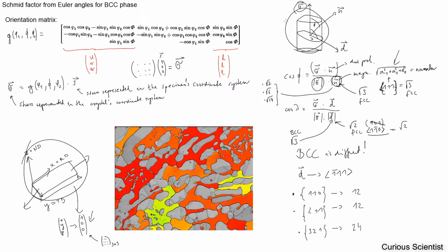And then what we can do is, for example, calculate the Schmid vectors with this formula here, or basically these two formulas. Sorry for the confusing jumps between the different parts. We also know that the Schmid vector is defined by this equation, the product of these two numbers, this guy and this guy. So this is the Schmid vector. And then we assign a Schmid vector to each pixel on an EBSD image, for example.